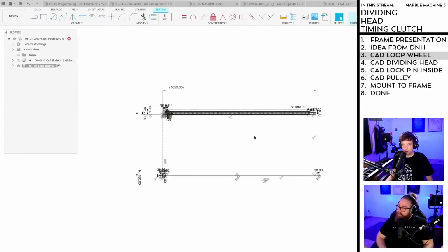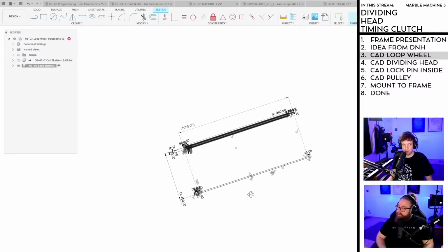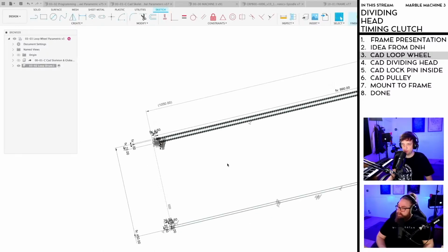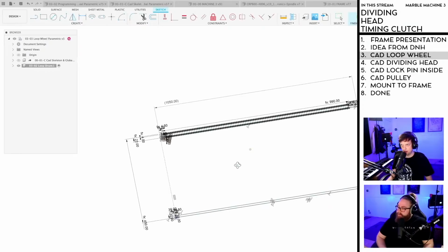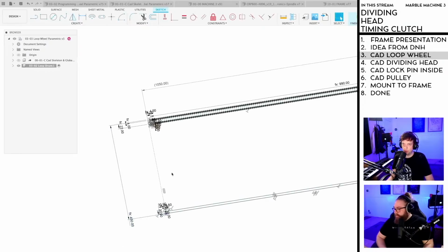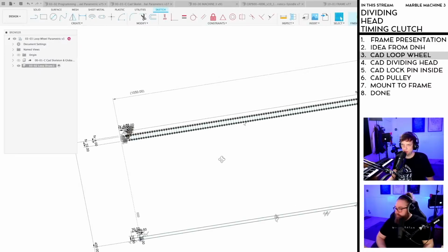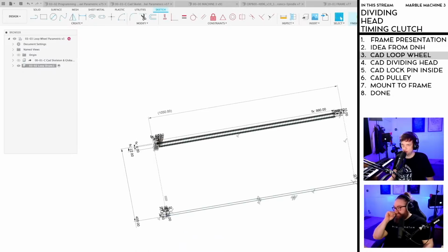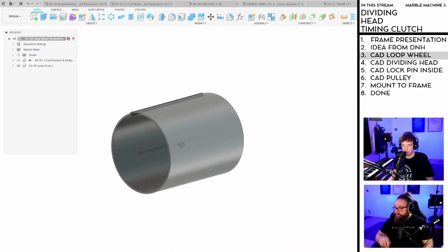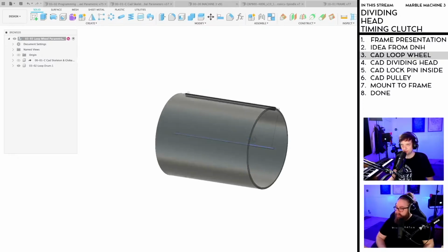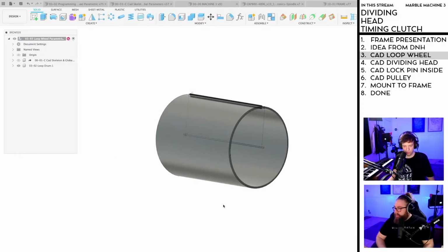And to make these drums, I'm using a flat sketch and a revolve command. And I need now to make a smaller drum. So I'm going to use 800 for the loop drum. So 800 divided by 2, that will make the whole drum smaller. So let's just check my parametric skills, and they are better than ever. So this is a smaller loop drum.